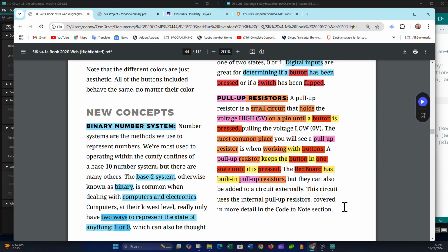That's not good for your program, because you're listening to that digital input for a reason: you want to do something when the button is pressed. But if the state is floating, the button will appear to have been pressed at different times, just based on electrical signal noise or whatever's causing the signal to float.